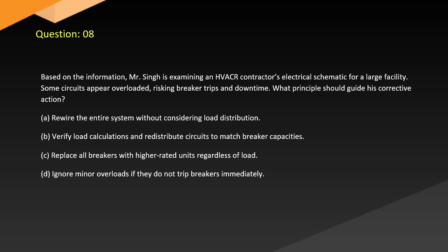A. Rewire the entire system without considering load distribution. B. Verify load calculations and redistribute circuits to match breaker capacities. C. Replace all breakers with higher-rated units regardless of load. D. Ignore minor overloads if they do not trip breakers immediately.